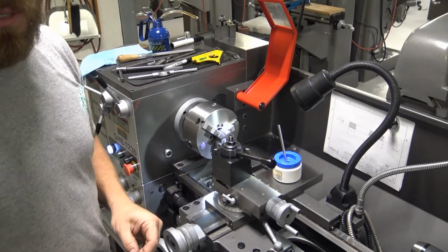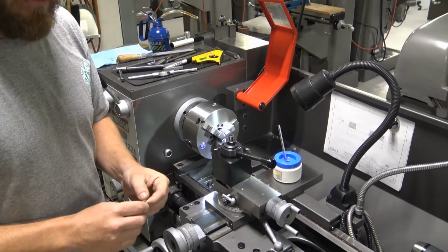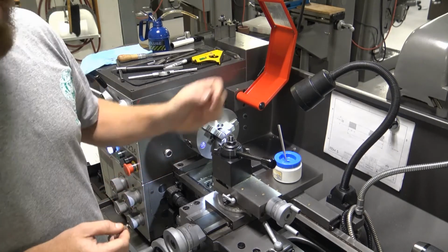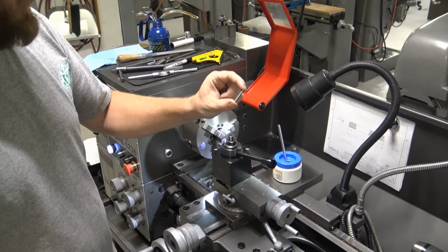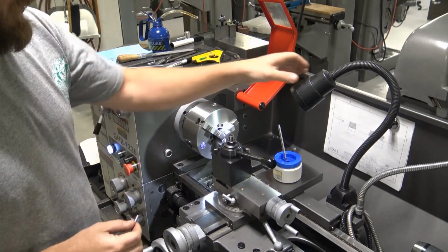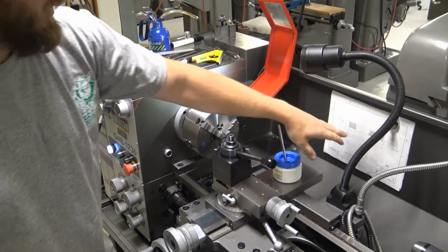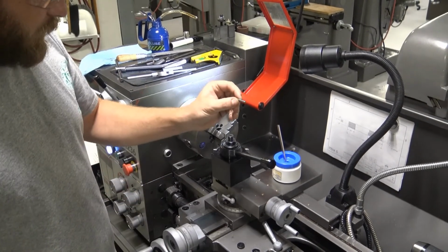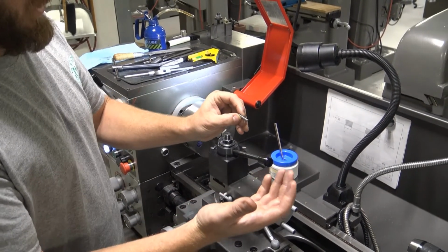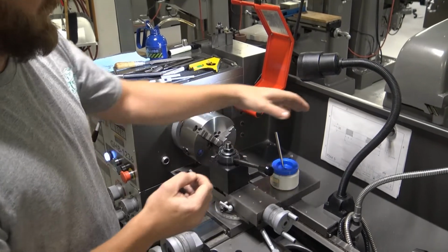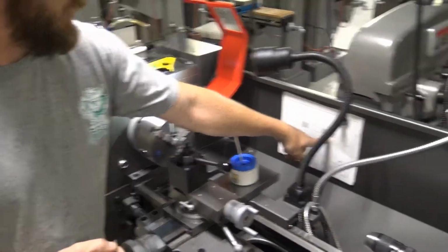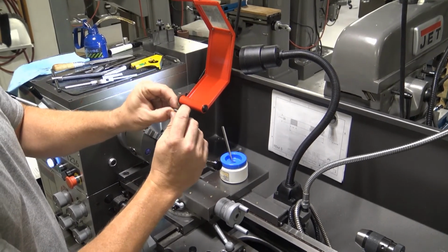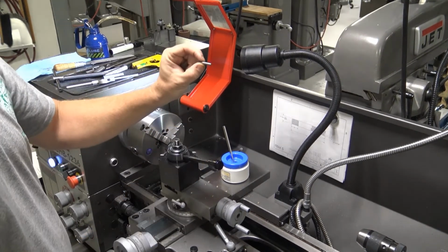We're back at the shop here for lab number 5. I'm going to show you how to make the threads right here. We are on part number 5. If you'll turn to that, I've got mine posted right back here. If you look at that, we talked about there being a 10-32 thread. Obviously it's going to be on both sides, and if you look, there will be a 1/2 inch portion and a 1/4 inch portion on this pin.